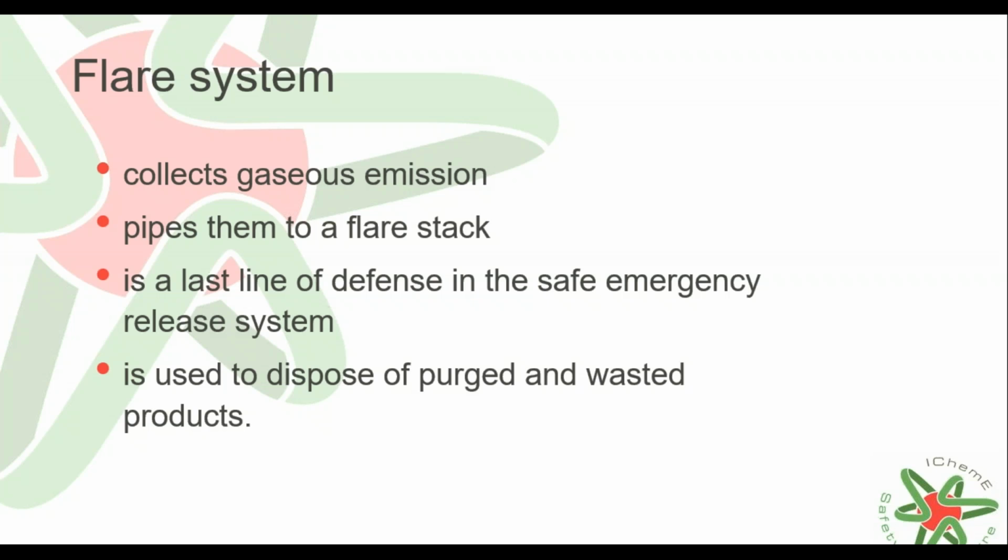The hazards associated with flare systems can cover a wide range, from embrittlement through corrosion due to low temperature, causing failure of the pipe collection system within the flare system, to explosion within the flare system, heat radiation, or, for instance, liquid carryover.